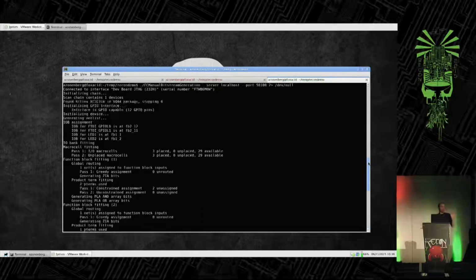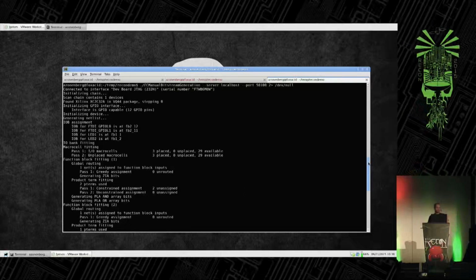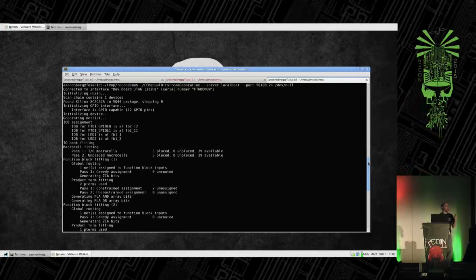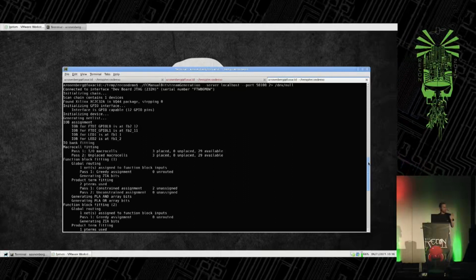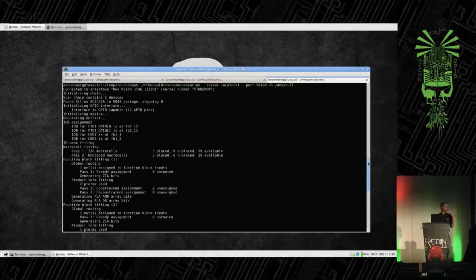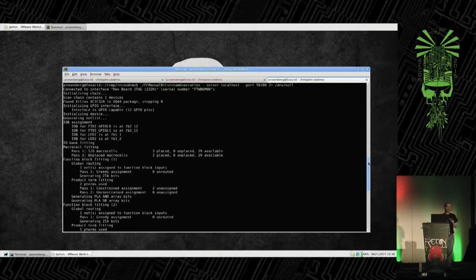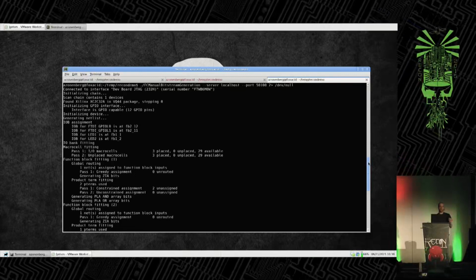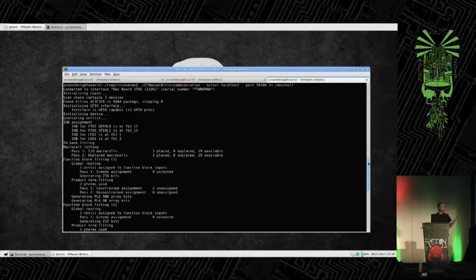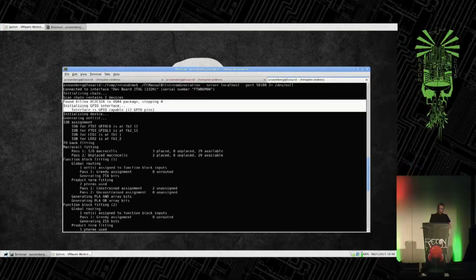One odd note: the CoolRunners are the only devices I've ever looked at in which the JTAG device ID includes the package as well as the device. What this means is that they've got a fuse somewhere in the die that says, oh, this is a TQFP, this is a BGA. I've never seen that on any other device. Every other FPGA or microcontroller I've used, the device ID was the same between different packages. Anyway, we confirm, okay, yes, the FTDI chip has GPIOs on it.